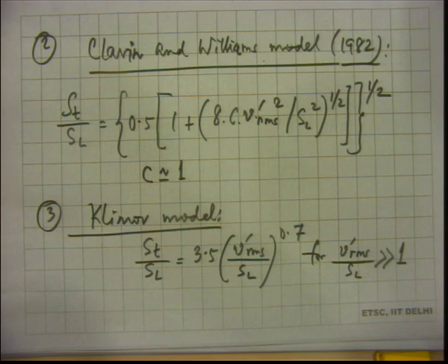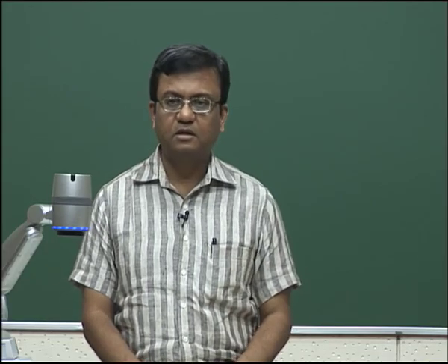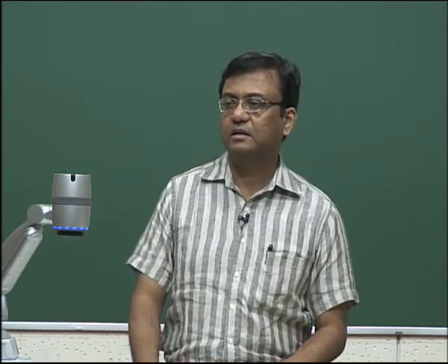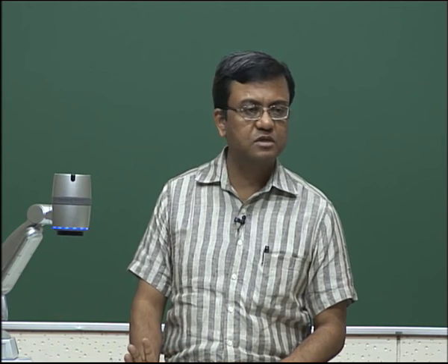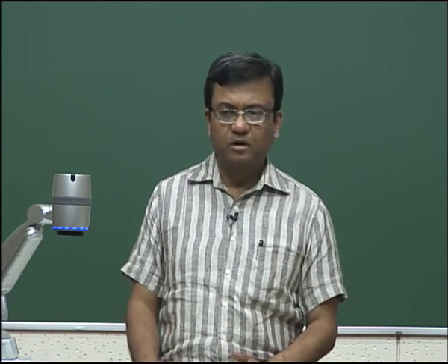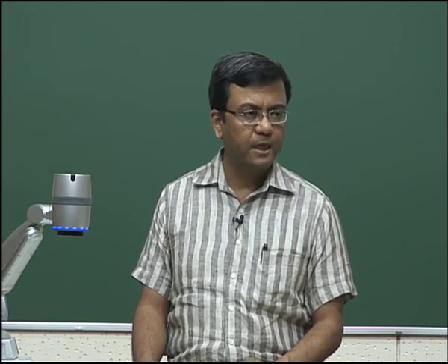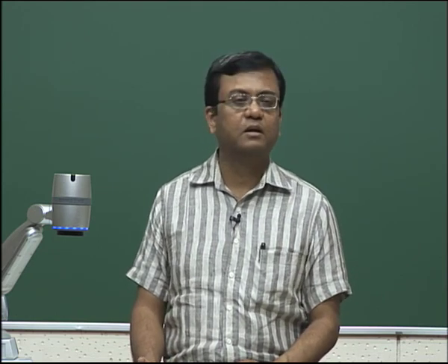Okay, so we ran out of time today, and tomorrow we will discuss a little bit about the other regimes. The other regimes will not take us that much amount of time. There is flamelet in eddies, and there is distributed reaction zone. This is the most important regime from the engine point of view, from a lot of practical combustion devices point of view. Remember that box that we saw in the regime diagram.